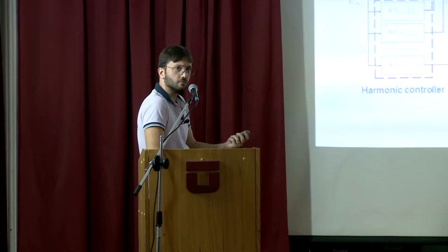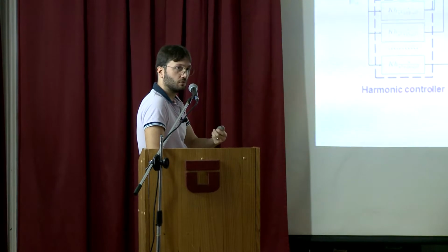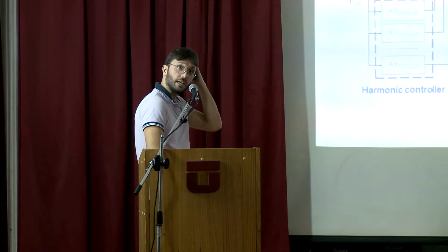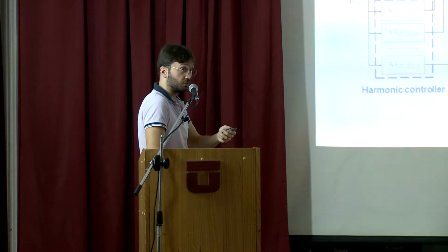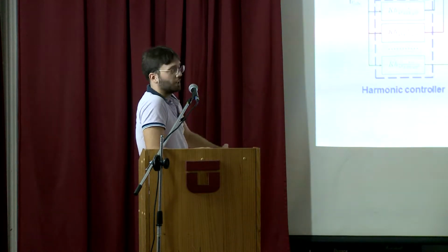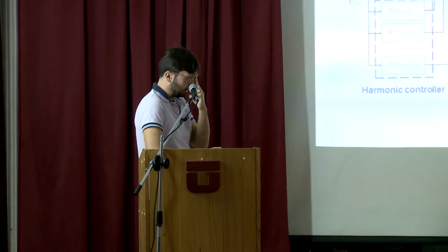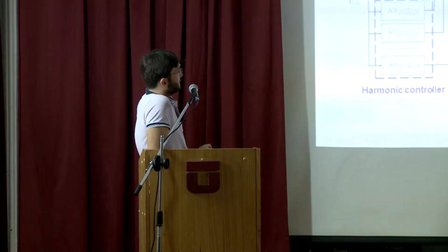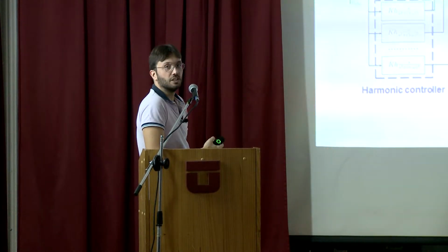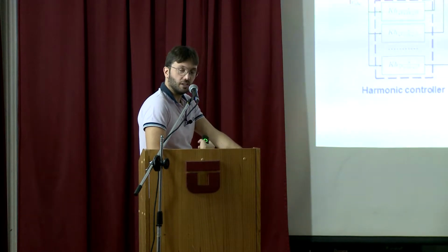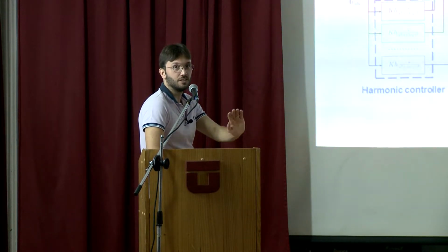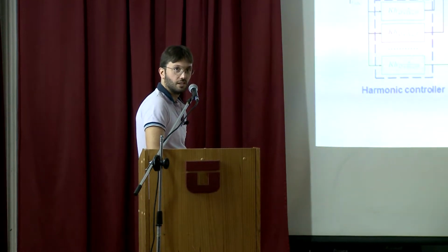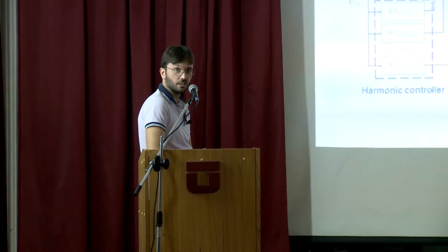So in an implementation for this control, and also what you will see in the simulation file that I made some days ago and will be distributed, there is an inner current control. In this case, the feedback is on the inverter current, but it is just one of the possibilities. The feedback for the inner current control can be the capacitor current, the grid current, any current.